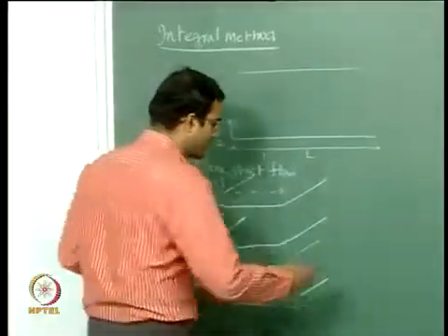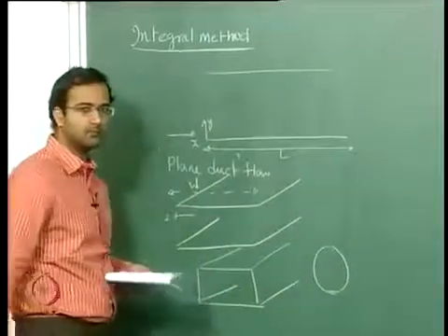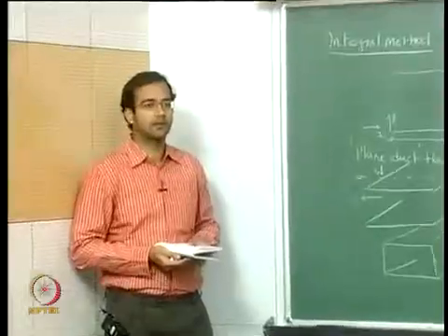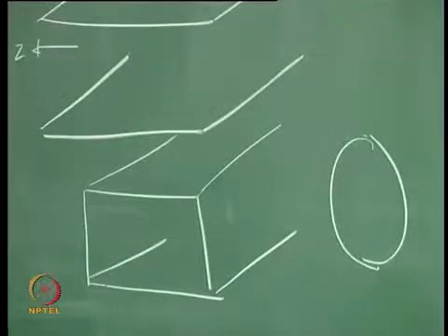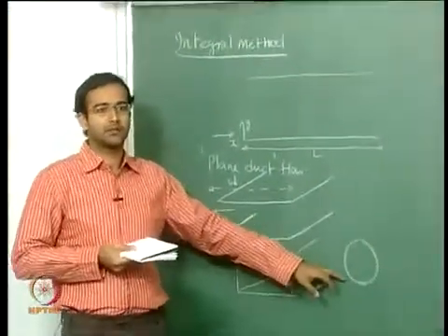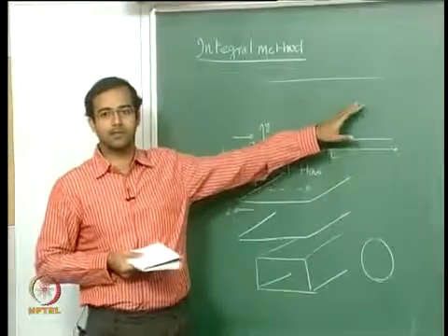Same with the case of a circular cross section. The boundary layers start growing simultaneously from all the walls, but in all these cases we have really not looked into the 3-dimensional nature of the flow. Whatever we have done so far with the circular cross section was just the 2-dimensional approximation of it.